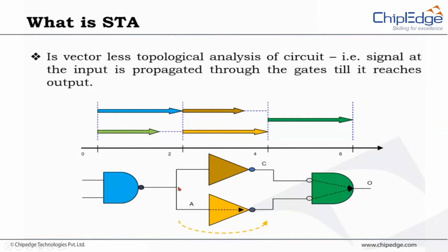And that is where the static timing analysis comes and bridges the gap, where it guarantees that I will look at all the paths for you. And it's going to come back and comprehensively give us an idea about what are the longest paths and shortest paths and so on and so forth, and optimize it or provide you analysis and data for taking decisions. See, STA tool is a pure analysis tool. Don't forget that. It doesn't translate a netlist or change the netlist and all that. It won't do those kind of things for you, but it gives you complete data for analysis and to take decisions about how to move forward, right?